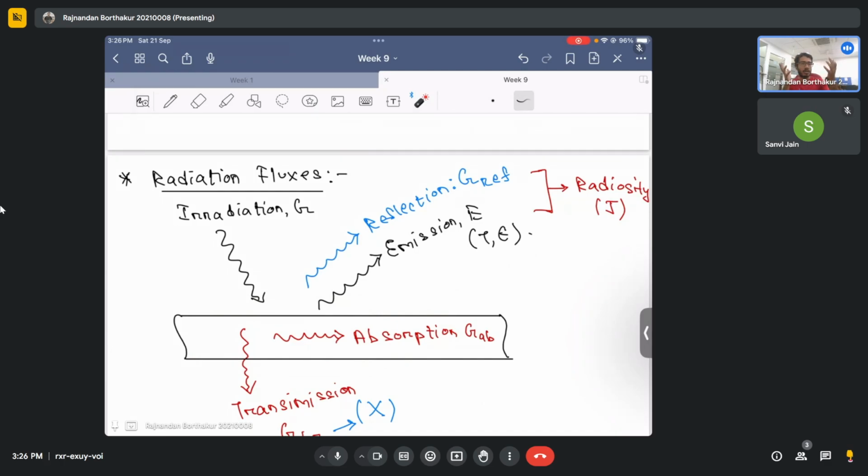For instance, if we choose a control volume and we say that the net loss or the net change in mass, we just simply write it as m dot out minus m dot in. Similar analogy goes for energy or the momentum fluxes. In the same spirit, if we say what is the net radiation that leaves a surface, it's simply the subtraction of the irradiation from the radiosity.